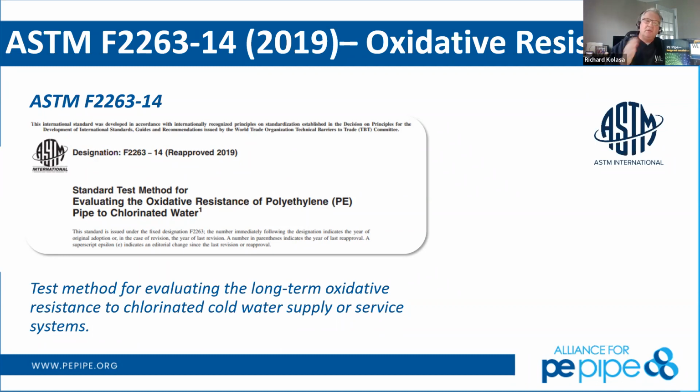So the water got very hot, and the chlorine or the disinfectant inside that tubing became very, very aggressive. When we look at oxidative resistance, we really had to open our eyes and ask what caused this, what was the true factor? Well, one was elevated temperatures. Two was elevated operating pressures, as they had fairly high pressures in that area as well. So the hoop stresses applied along with the oxidative effects were really important to understand, which we now look at as an ORP, or an oxidative resistant potential.